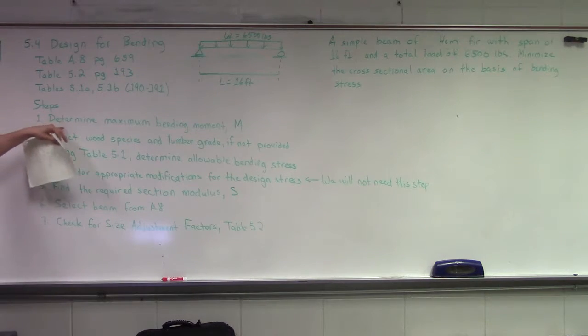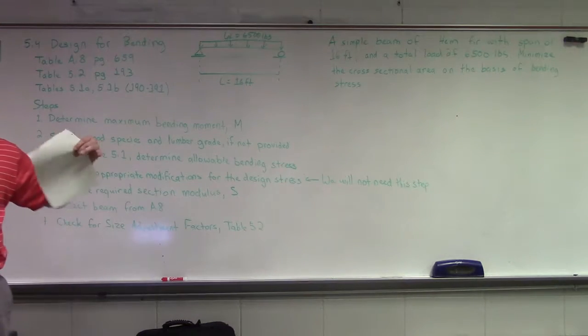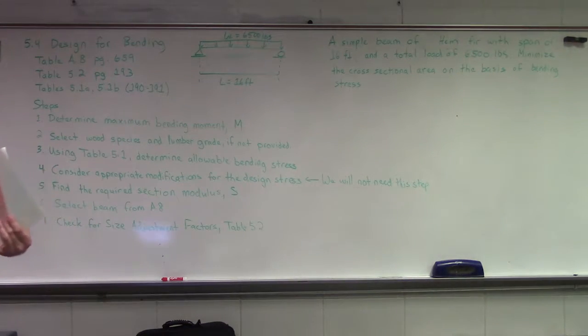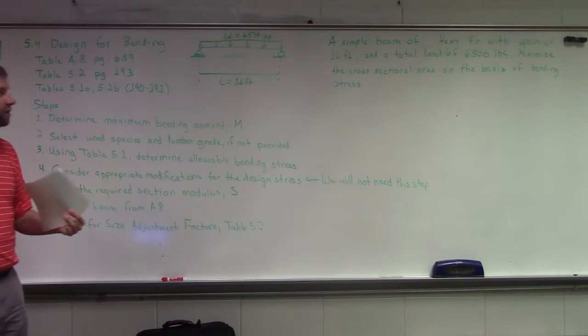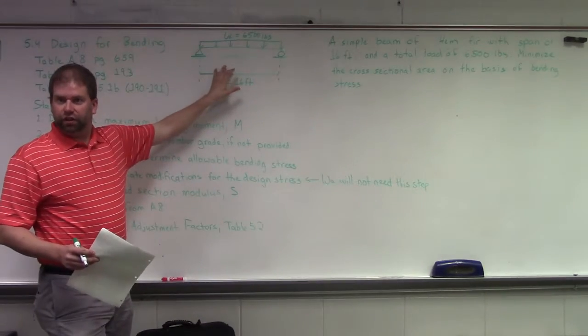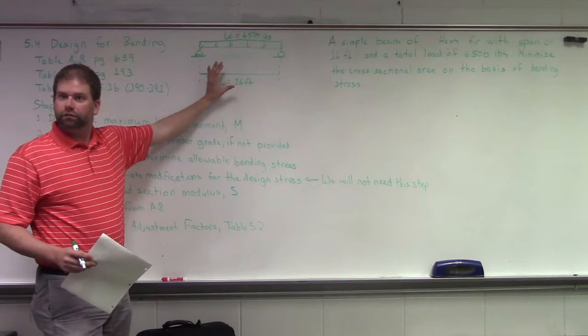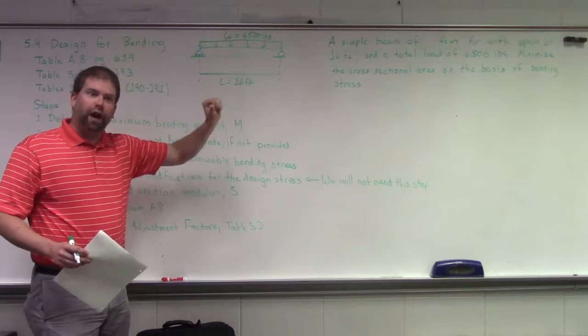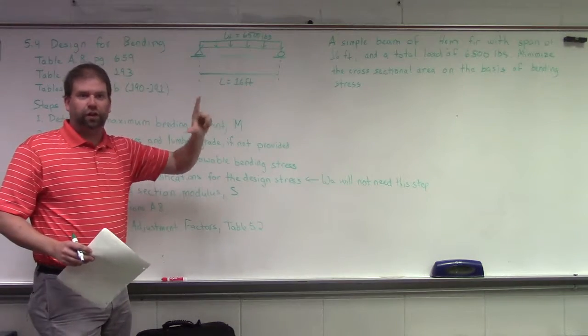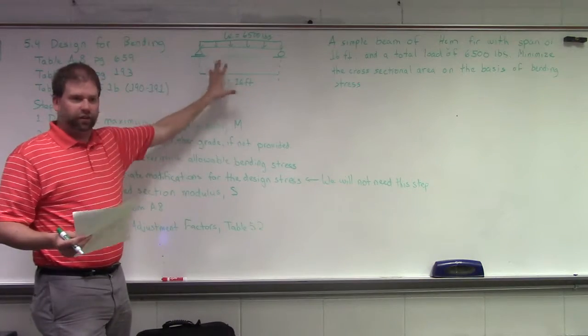The first thing that we'll look at, we'll need to determine the maximum bending moment. Now, one of the things that we didn't have time to do when we were in the chapter on bending is look at all the different moment equations for our various loading conditions. For your homework, this is the only condition that you will have. It will be a uniformly distributed load. One of the problems, you will have a live load and a dead load that you will have to factor. But once you factor it, it's the same problem.